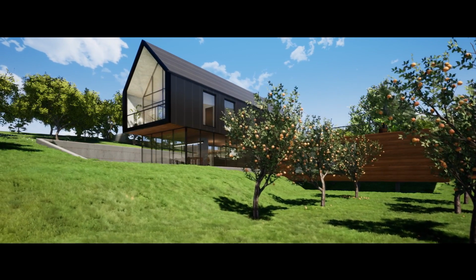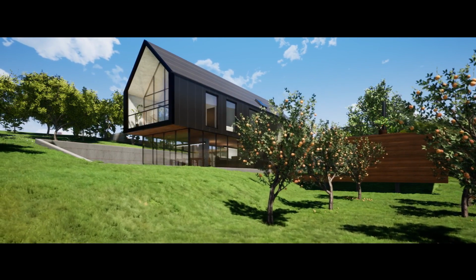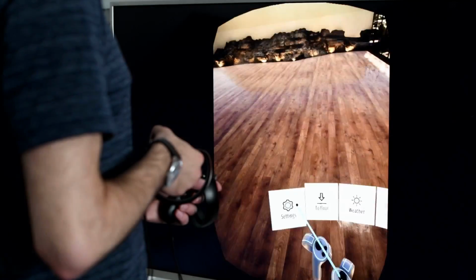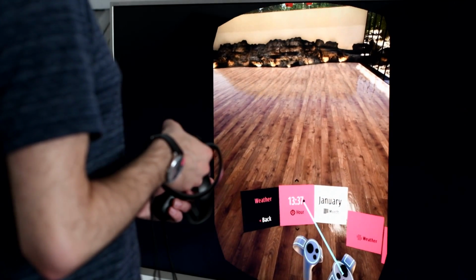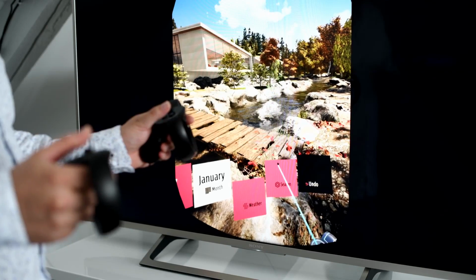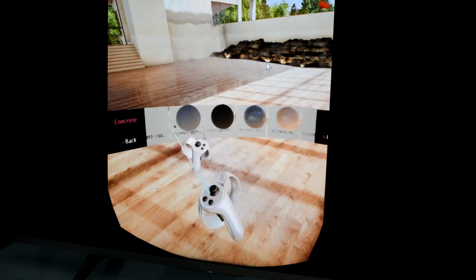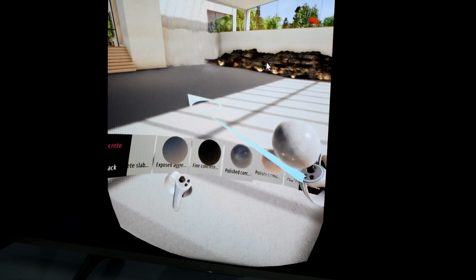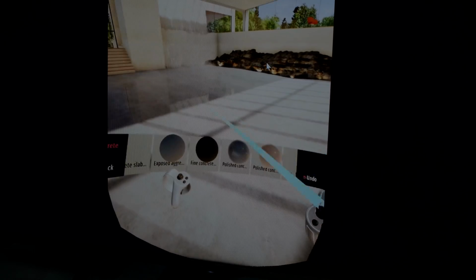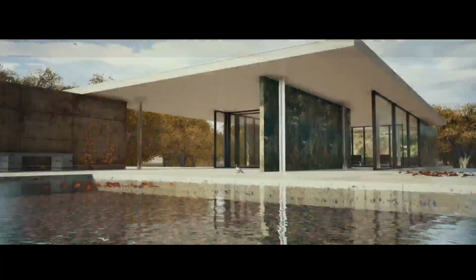Then, of course, you keep working on your 3D model, and you just update the changes as you go. Everything you have set up in Twinmotion won't be lost. For example, if you have set up just the interior of your project, then you start to work a bit more on the exterior, everything in the interior won't be changed. You keep working on the exterior, you just update. Just the new modification, the new piece of geometry, will be added to Twinmotion.